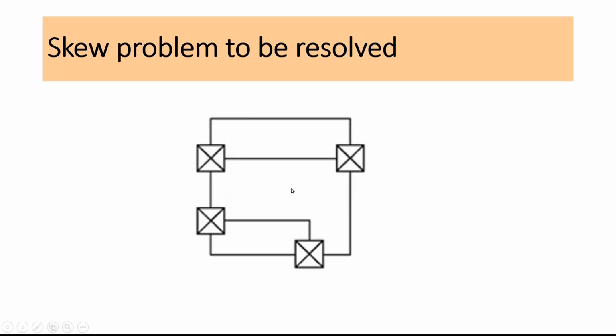Friends, as shown in the figure, here I have shown two paths from input to output port. First one is straightforward. Second one is a little bit complicated. So if you leave these paths unconstrained, then definitely there will be a huge amount of skew between these two data lines. But this skew is not desirable. So we have to constrain these data lines.